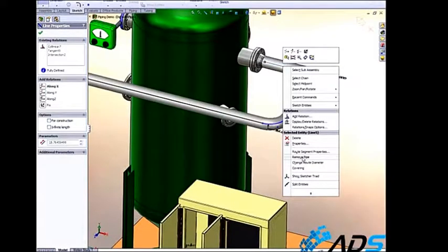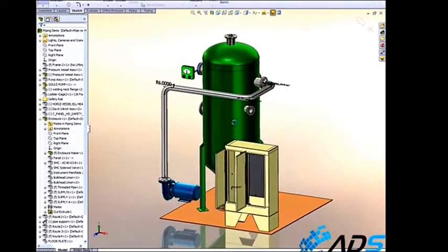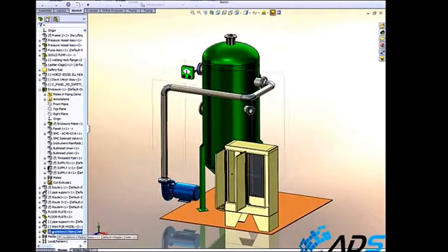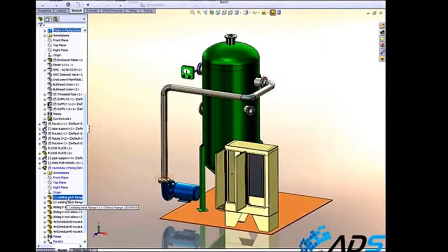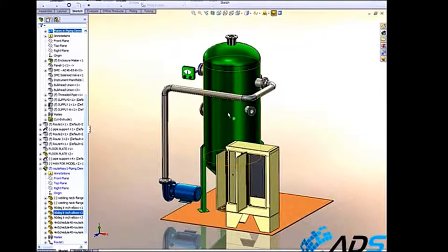Now we may want to tidy up our design, so here we're just going to remove the pipe and weld directly to the flange. Now at this point, all we've done is dropped in a couple of flanges and drawn some lines. SOLIDWORKS has taken care of mapping all the pipe information onto that. You can actually see we've created a subassembly. This subassembly contains 8 components, the 2 flanges, 3 pipes, and 3 elbows. So all this gets done automatically by SOLIDWORKS.